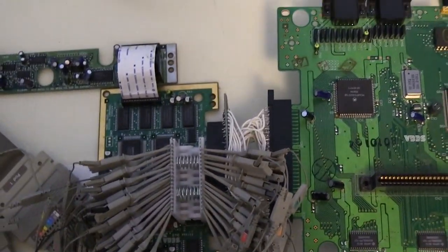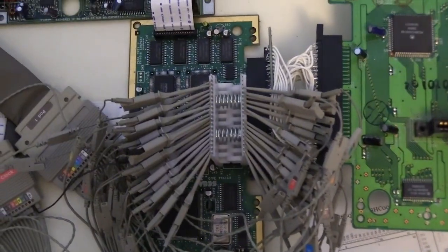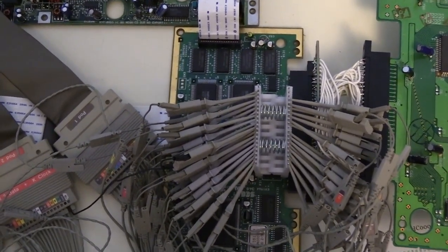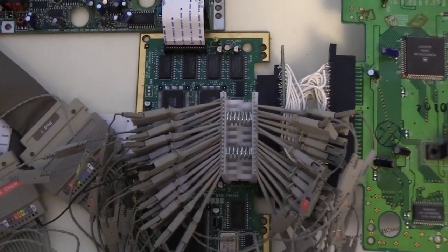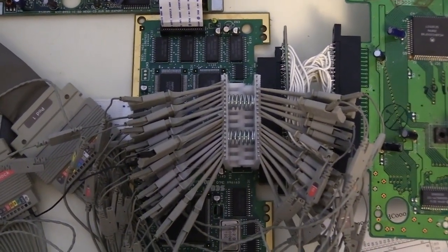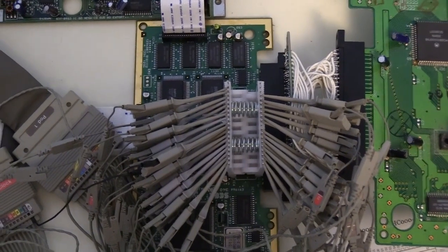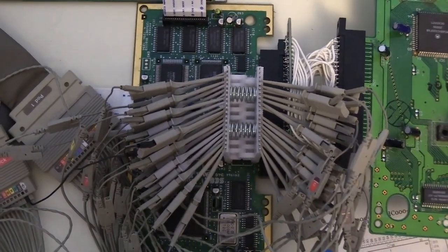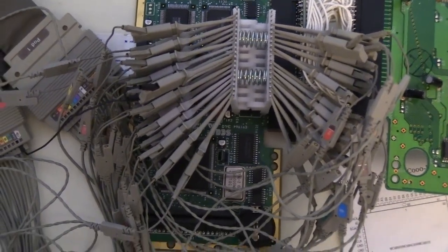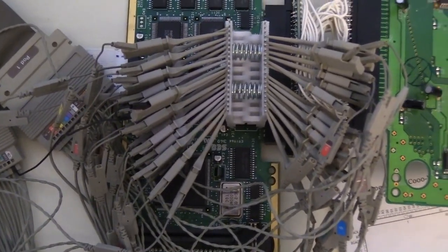And then there's 2 memory control lines on the EPROM. There's a chip enable, which brings the whole EPROM in and out of activation on the circuit. And then there's also output enable, which only gets brought high when the CPU wants to actually read the data.